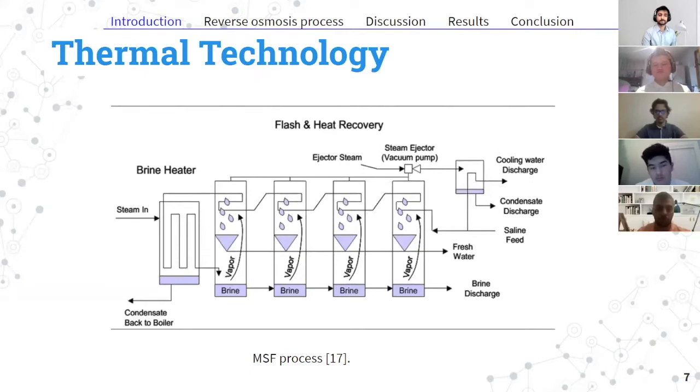So thermal desalination, arguably the most primitive technology, is the process of converting saline water into water vapor. This vapor contains very few impurities and when condensed produces drinkable water. Thermal techniques include multi-stage flash, multiple effect desalination, thermal vapor compression, and others.